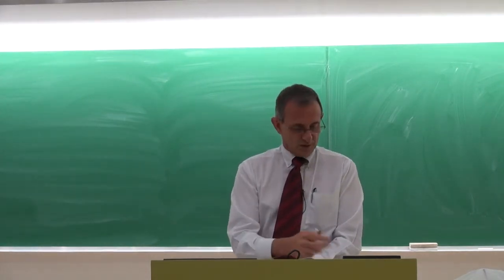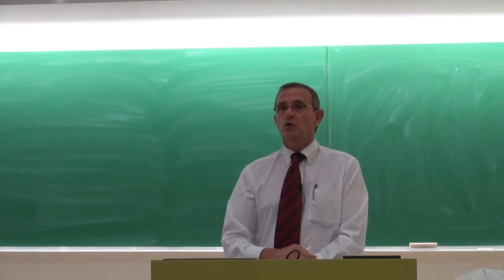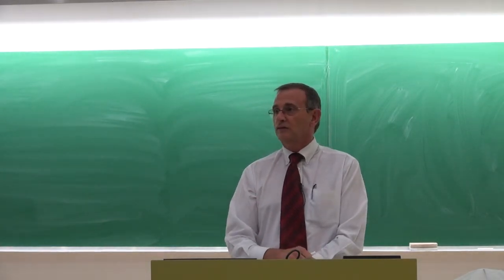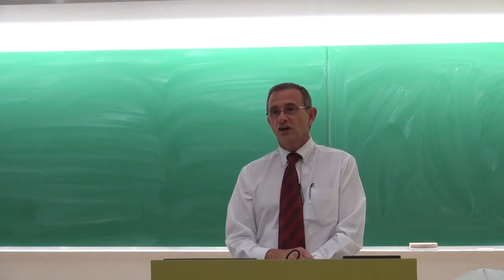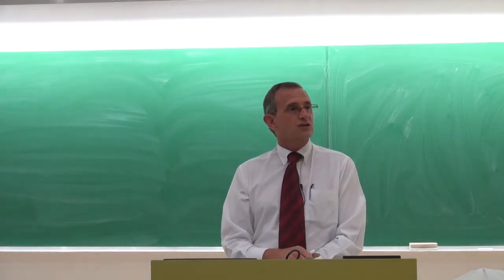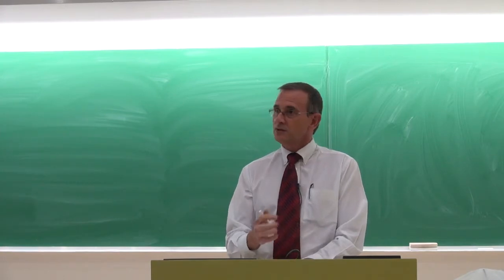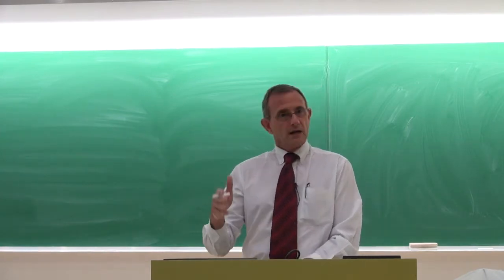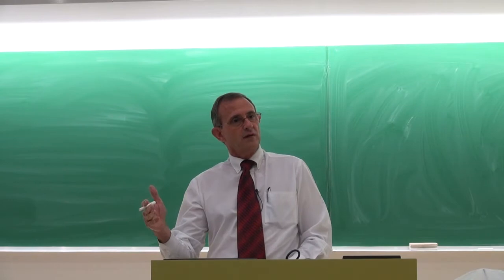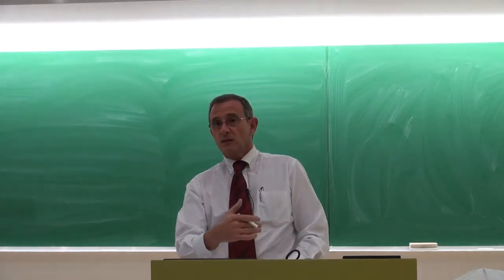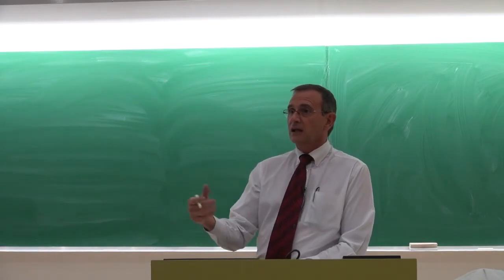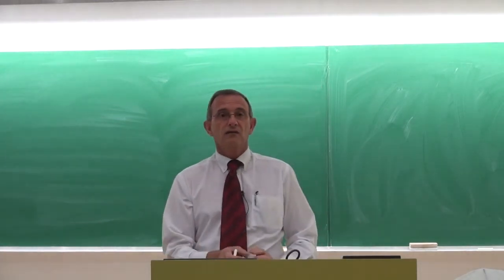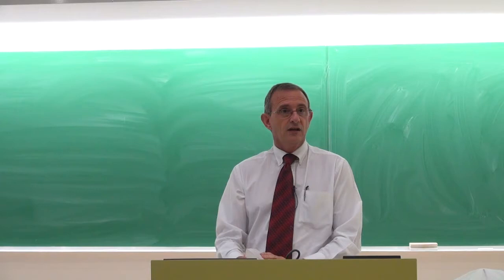So specifically paragraphs 9.4 and 9.5, we are not going to work through every one of those configurations. All of them are similar in the sense that the Nusselt number is a function of Reynolds, Prandtl, Grashof, and so far the Reynolds number doesn't play a role, and you will have to determine that and get the equations, and the fine print is very, very important.